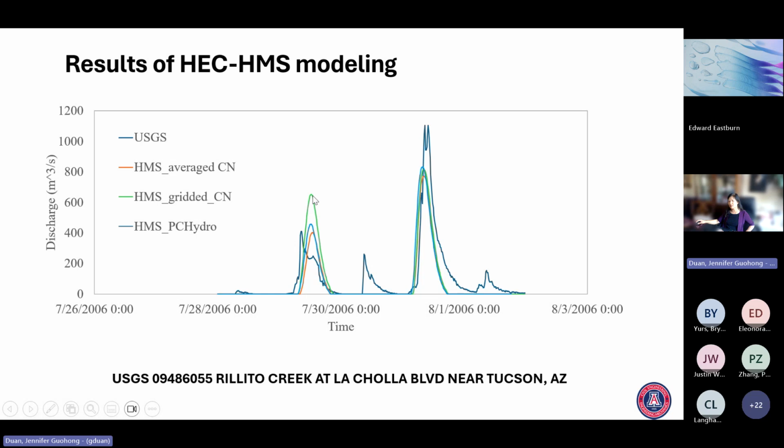The probable reason is that the current land is fully developed, with a lot more development. So the map shows larger curve numbers than the 2006 situation. That's why we predict a larger runoff. In fact, that year we saw less runoff because 2006 was not as developed as today. But anyway, the real peak is under-predicted. There are many reasons you can explain. Maybe the curve number method itself is not adequate, or some other reasons. But anyway, those are the results.